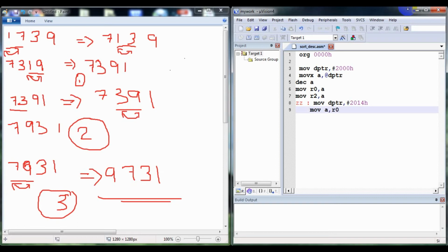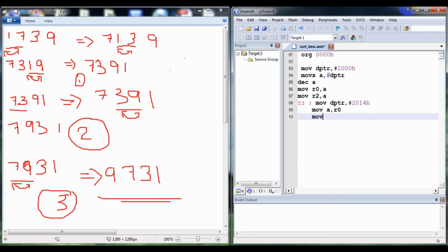We are using a subtraction in the later steps. So by subtracting, the output will be saved in the accumulator register. Hence, the accumulator value will be changed. So if we want to take the R0 value to R2, we have only one way, by taking it through the accumulator.